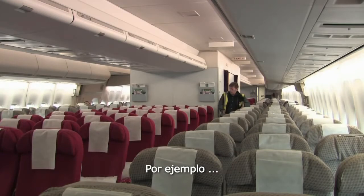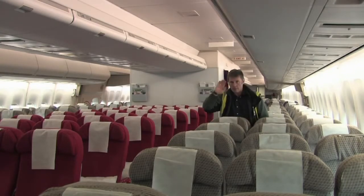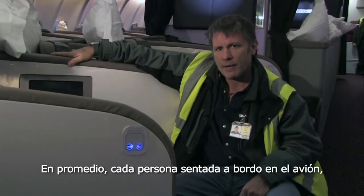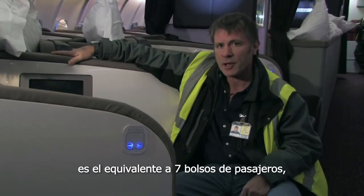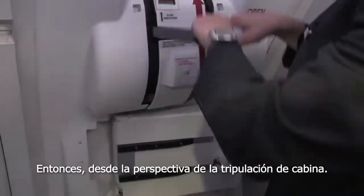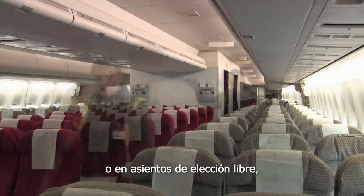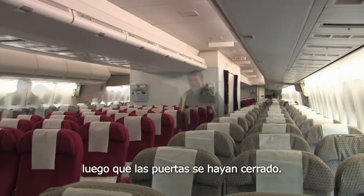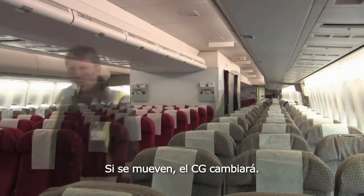For example, here, or here, or here. Just remember, on average, every person sitting on board an aircraft weighs the equivalent of 7 passenger bags down in the hold. So, from a cabin crew perspective, whether you're operating an allocated or free seating flight, be aware of passengers playing musical chairs after the doors have been closed. If they move, the C of G will change.